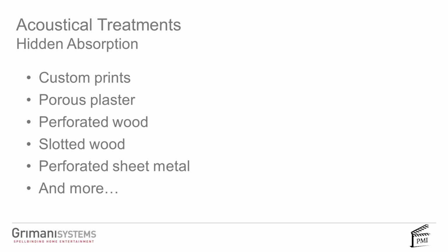And it works, just don't do everything absorptive, because again, that would over-absorb it. There are perforated woods, slotted woods, perforated sheet metals. There's a whole bunch of different materials you can cover the absorbers and diffusers with to not let them be ugly warts on the walls.